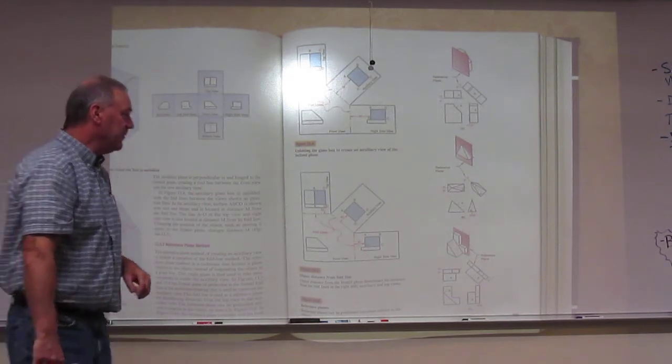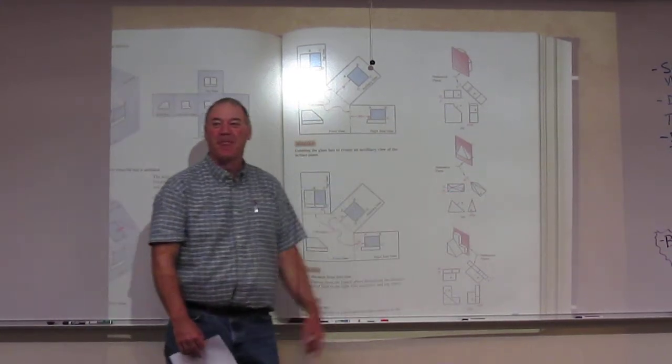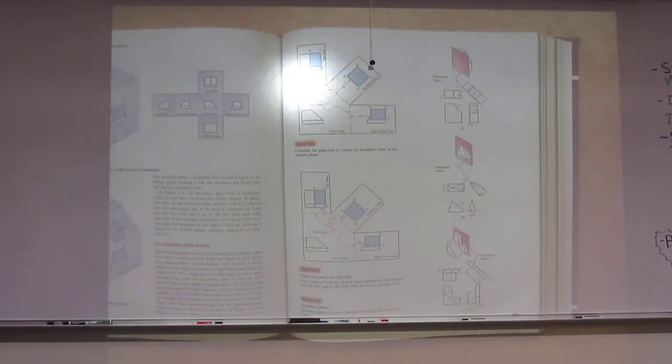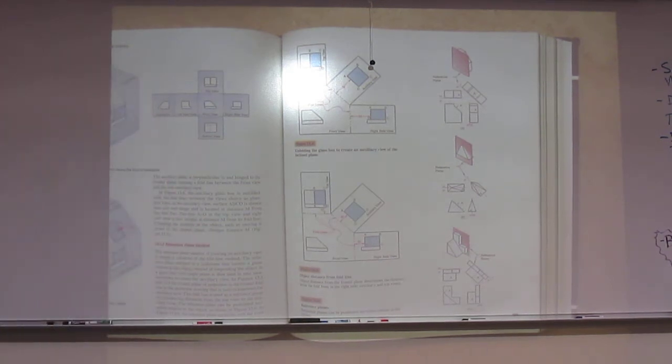And in fact, when you do circular features, that's pretty much what you're going to do every time. It is that center reference plane. So two ways: you've got the fold line method, and you have the reference plane method. Both of them in essence work the same, we're just using a different datum to transfer the measurements.